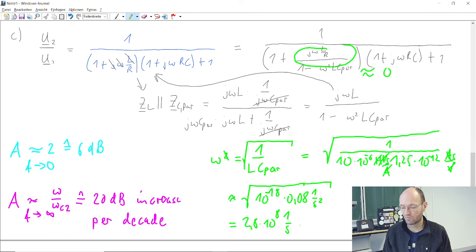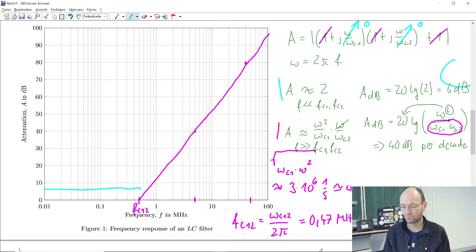And now we can convert this into a frequency. I checked, it's 45 megahertz. So this corresponds to 45 megahertz of, let's say, usual frequency, right? Because this is something like 280, and 280 divided by 6 is 45. Okay. So this means that at 45 megahertz, which would be somewhere here, so here is 10, 20, 30, 40, at 45, somewhere here, we would get a very high attenuation.